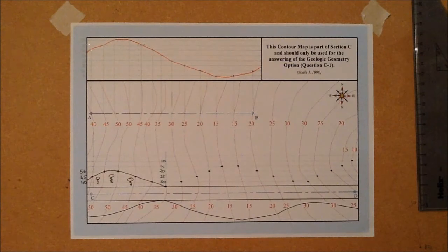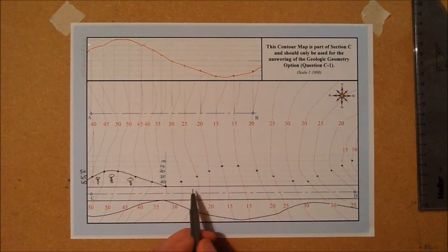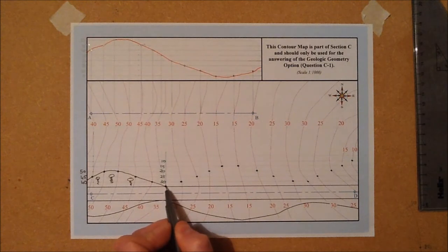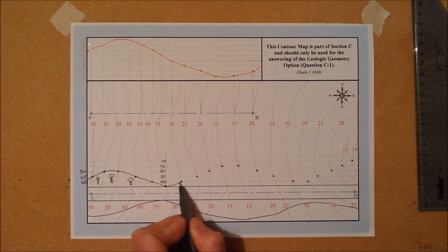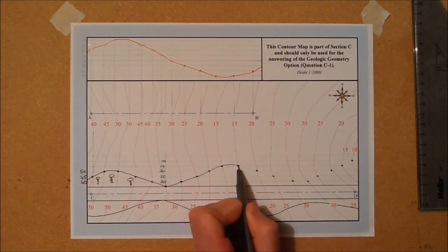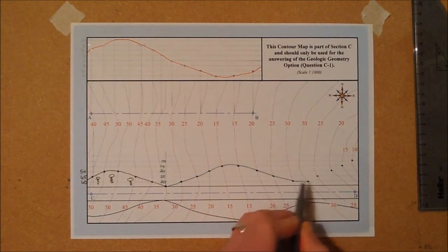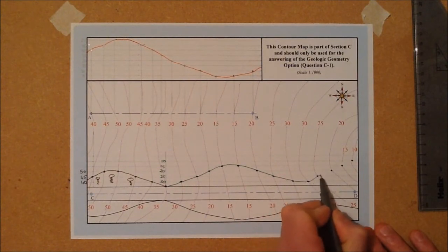Now I have all those points plotted. I'm going to draw this in, and because our cutting and our embankments are going in different directions, I'm going to draw them in different colors as well, just to make them easier to identify. When you're looking at the drawing as they get more complicated, it's much easier to identify straight away whether it's a cutting or an embankment that you're working on.